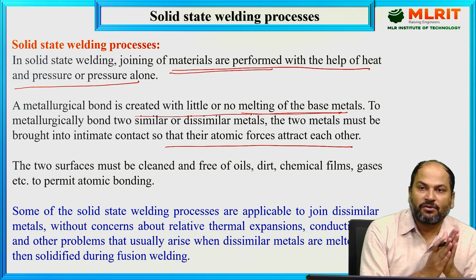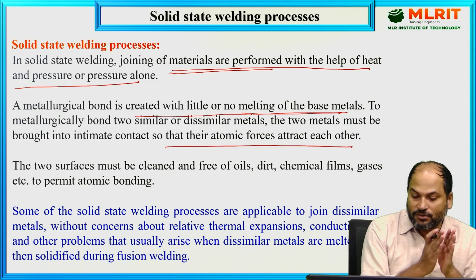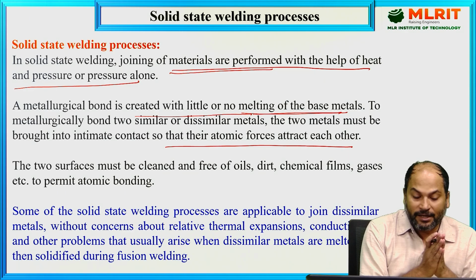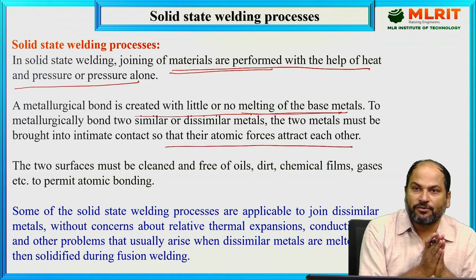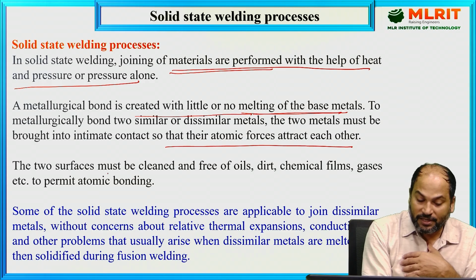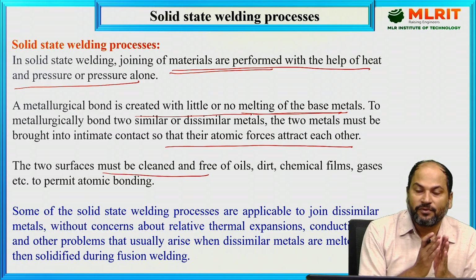Okay, now there should be proper contact, and whatever contaminations are there on the surface need to be removed, so that the two parts we are going to weld together will have intimate contact, so that the attractive atomic forces will come into the picture, and the two parts will be welded together. This is very, very important to understand. The two surfaces must be clean. Yes, these two surfaces which we are going to weld together must be clean.